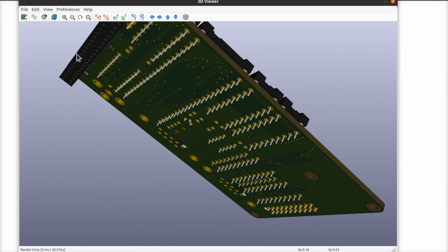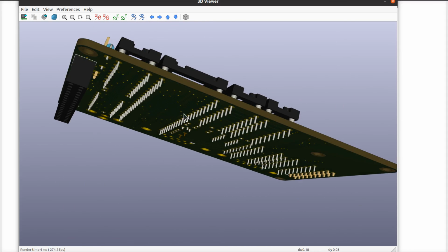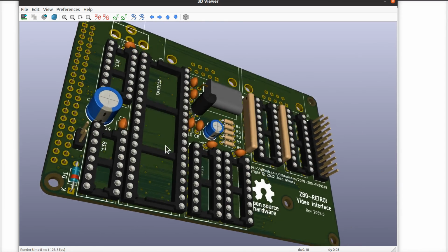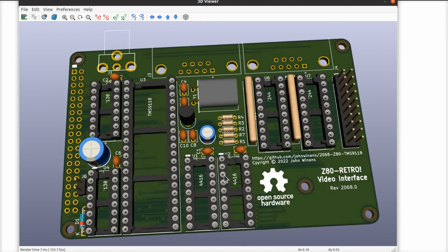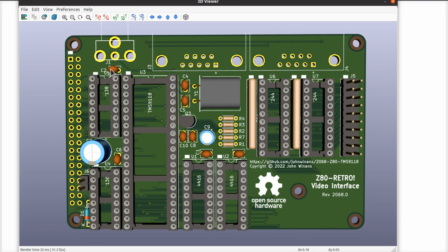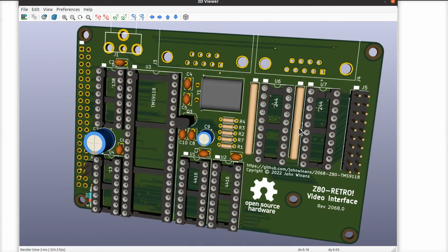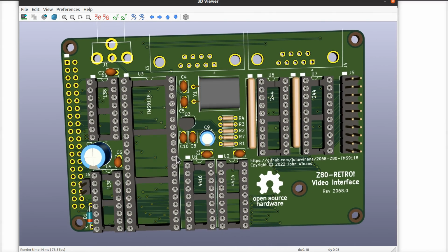All right, we got another one of these buggers on the back here to jumper it onto the retro board. No parts on the back. All through hole. And we could obviously put surface mount caps on there. And that's what I would do anyway in this case, because these things cost so much money. And I've got reels and reels of tiny little bypass caps. And certainly as we go, I'll probably find things I want to tweak or change. So I won't waste expensive parts. I'll waste cheap ones.